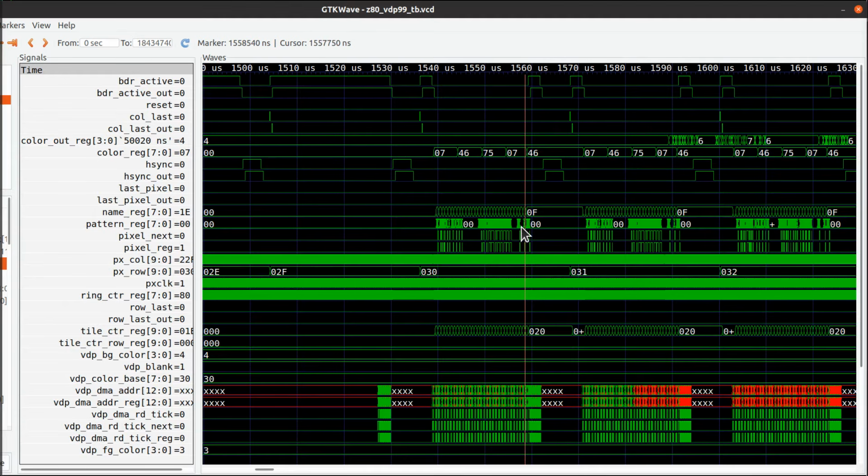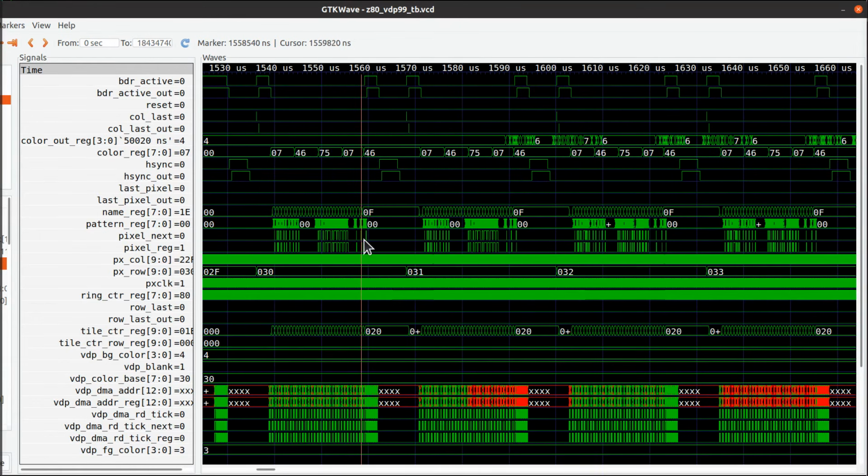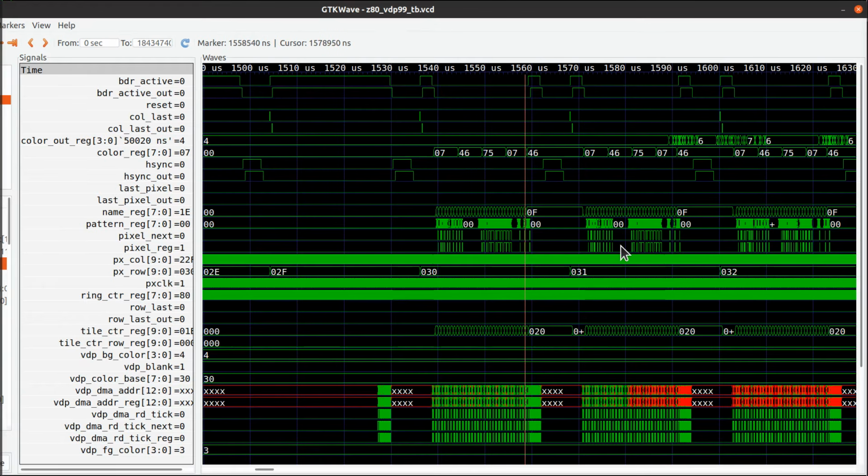Here's one row in terms of time, because you can see the border, and then you see pixels going out, and then the right border, and then you get the horizontal sync. You see a border, active display, border. Now, you see this pattern here? It looks the same as this one over here, because it is, right? This is your 2 VGA rows rendering one VDP row, okay?